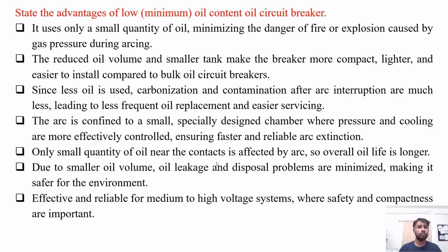The arc is confined to a small, specially designed chamber where pressure and cooling are more effectively controlled, ensuring faster and reliable arc extinction. Only a small quantity of oil near the contact is affected by the arc, so overall oil life is longer. Due to the smaller oil volume, oil leakage and disposal problems are minimized, making it safer for the environment. It is effective and reliable for medium to high voltage applications where safety and compactness are important. So these are several points of advantages of low oil content circuit breaker.